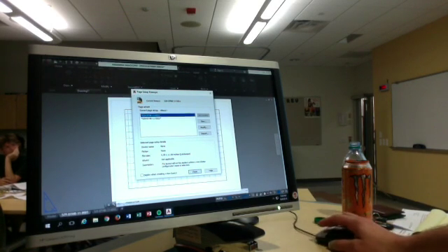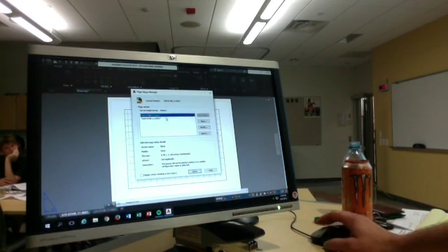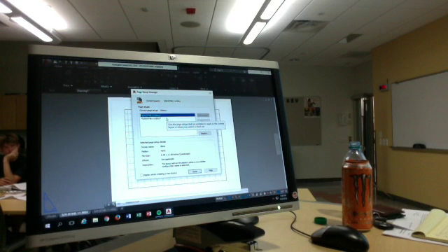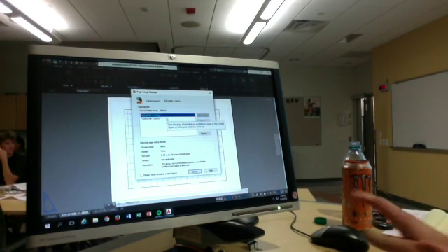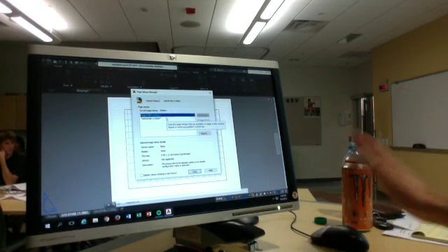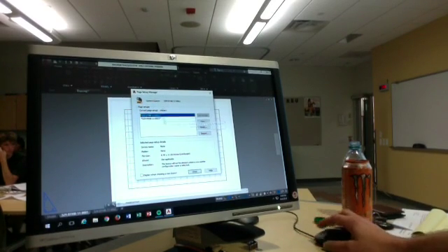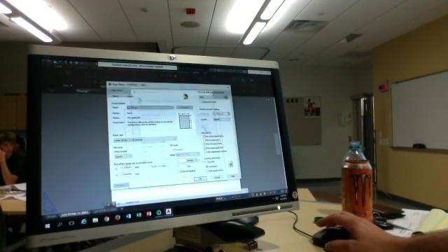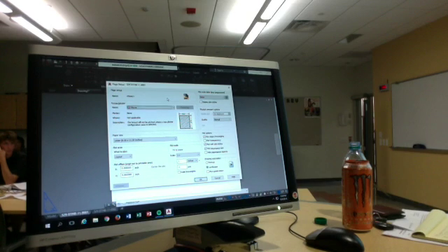In order to do that, you can click which sheet you want. Notice model is not listed in there. You don't want to print from model space unless you just need an example and you're going to mark it up. You typically always want to print from paper space. So you click on modify. Like I said, this looks exactly like when you go to print something, but this is the Page Setup Manager, which is still slightly different.